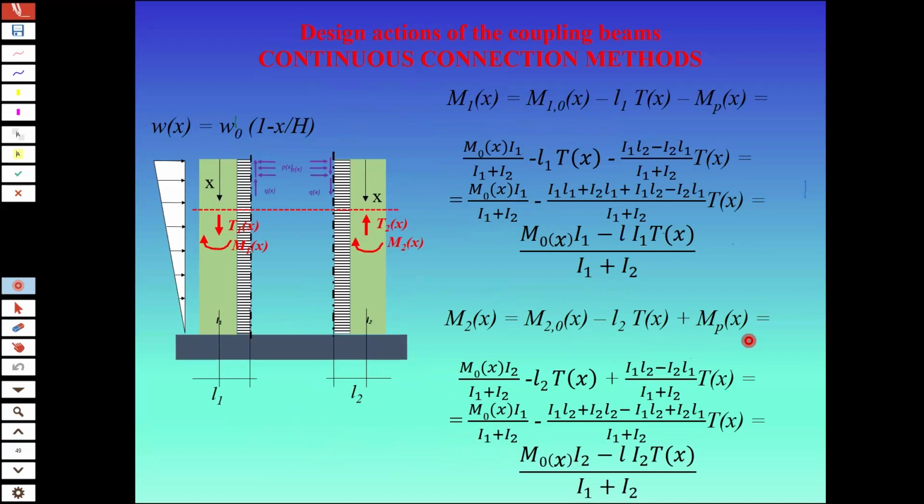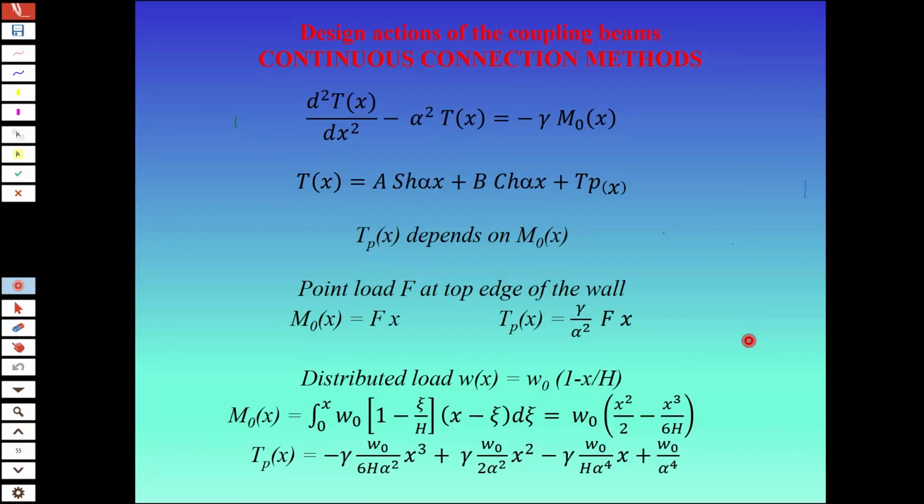You see this force T actually, if you start from the top, the force T is the integral of the shear forces in the coupling beam. So this equation here, you solve, and you find that T is hyperbolic sine and cosine. If you want to know Q, just calculate the derivative, because if T is the integral of Q, Q is the derivative of T. And then there are always the boundary conditions, which depend on this, and you find some examples there.